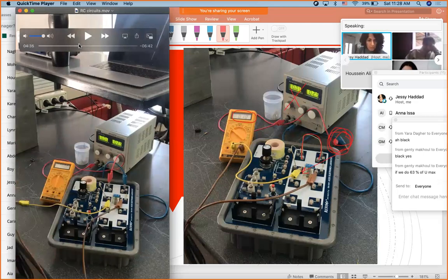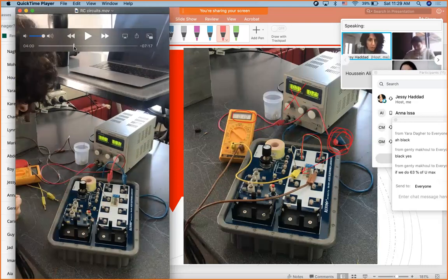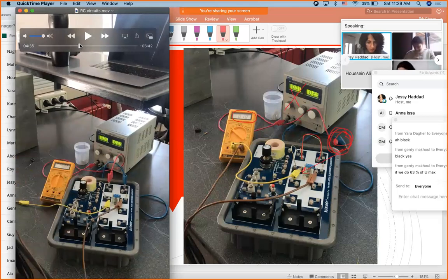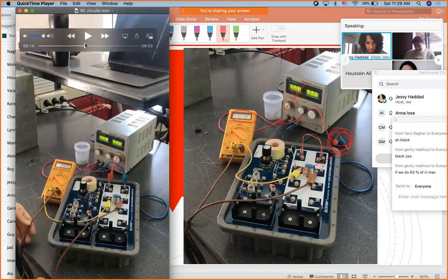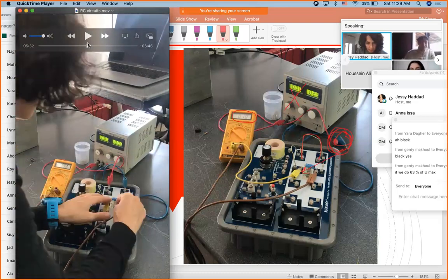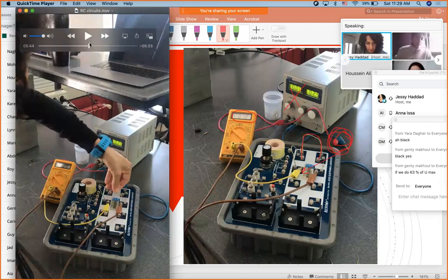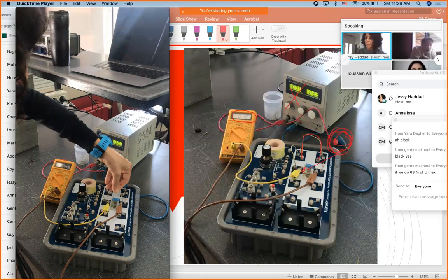All right, I'm getting ready with my voltmeter. I think the voltmeter is on 2 decimals, which means scale 20 volts. Okay, now let me show you how I short circuit. Okay, you see, I'm explaining the fact again. All right, you see, I short circuited the capacitor on purpose because I want to start from 0. The capacitor will fill itself so quickly that you cannot start from 0, you have to empty it.